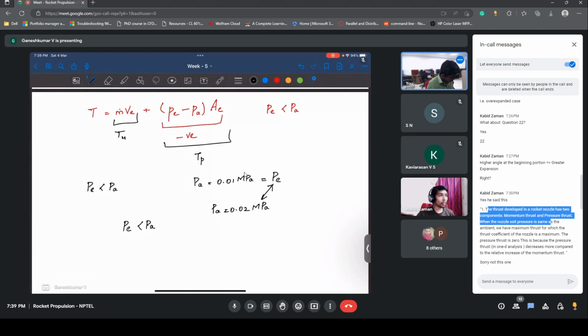In a separated flow, it provides high pressure at the nozzle, therefore the nozzle can adapt to the altitude. In the book also, it was told that separated flow would be helpful because there will be a high pressure gradient. The thrust from the nozzle with flow separation is more than the thrust corresponding to the same area ratio for which flow separation has not taken place.